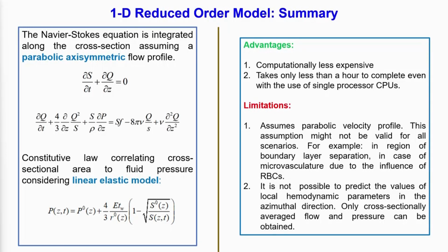Now, this does not close the model, because you also need a physical law that will relate the pressure with the area or the radius. Yesterday I gave you a homework where I mentioned that for a thin walled cylinder, say you have that formula, the hoop stress sigma is P into R by T.